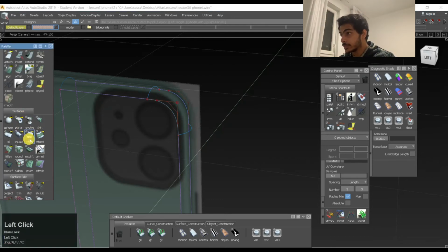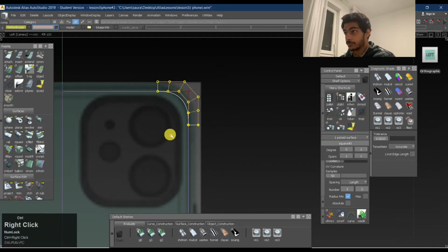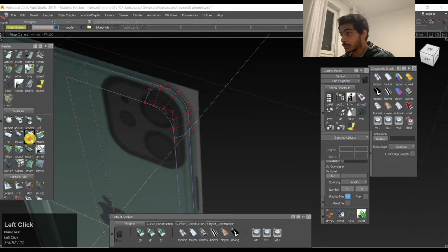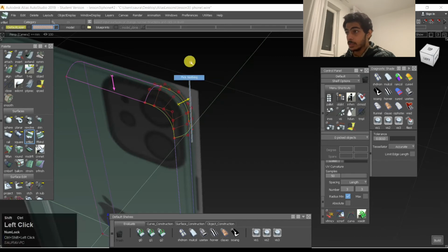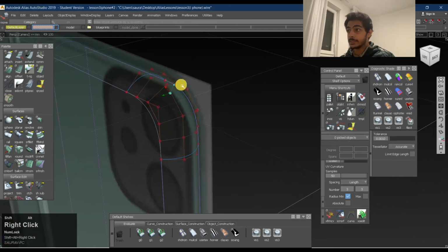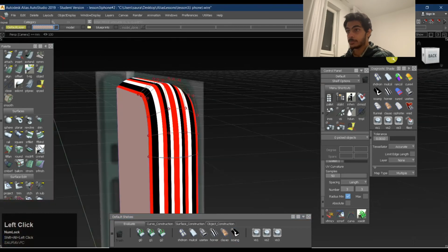the surfaces, surface fillet. We'll pick all these surfaces, right? Only if it's in tangency is it going to work. If it's only there in position, it won't work. So suppose if this point would have been a bit up, and if I would have done the surface fillet over here, you see how it broke? It's not anymore in tangency. That's not what we want. We want it to be in tangency. It's okay if it's not in curvature, but at least tangency should be maintained.